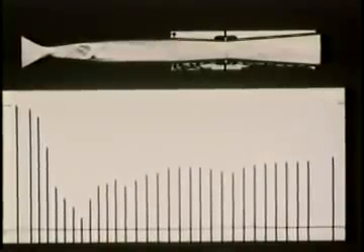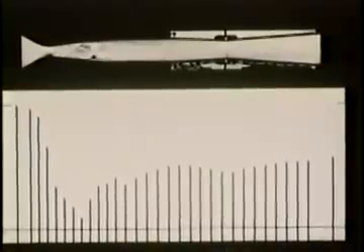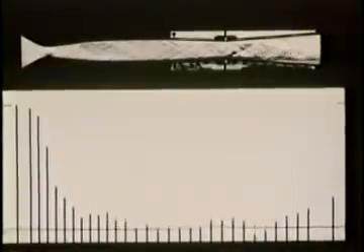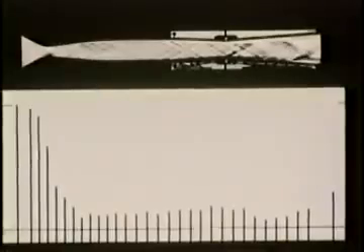When the channel is running, we expect to be able to reduce the area of the second throat, because now there is no strong shock wave in the nozzle to degrade the stagnation pressure of the flow. But when we try this, the flow becomes blocked almost immediately. We have to reopen the second throat in order to restart the channel. In this close-up, we can see part of the reason why we cannot close the second throat to the same area as the first one. We have to allow room for these thick boundary layers, which are not carrying their share of the mass flow.